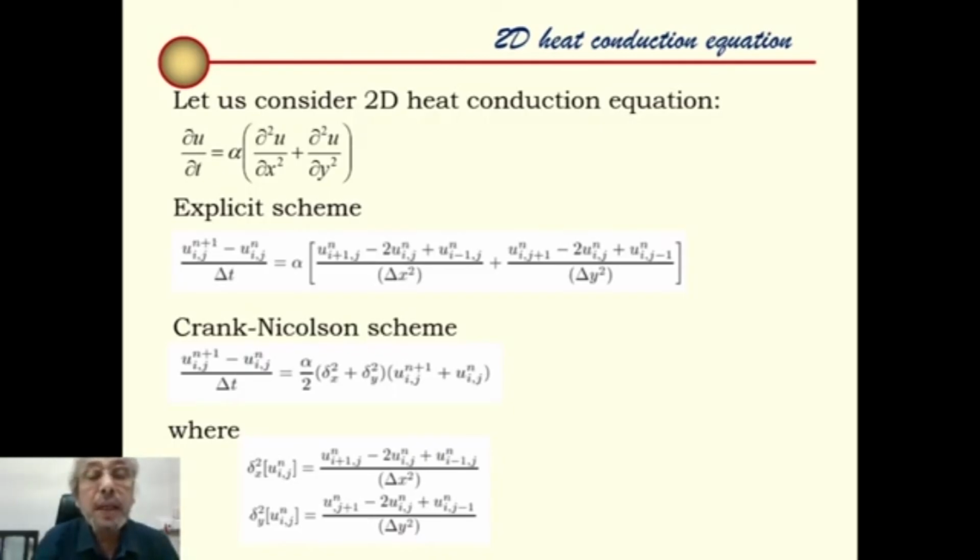So now if we look at the two-dimensional heat conduction equation, with the space variables, we have second derivative in x and second derivative in y, in x and y direction, maybe on a plane, and then we are progressing in time direction. Now here also we can write an explicit scheme. That means central differences in the x direction of the variable involving eastern neighbor and western neighbor, uij is the point of interest at nth level, divided by delta x square. Again, uij, its northern neighbor, uij plus 1, and uij minus 1, southern neighbor, divided by delta y square, simple central difference.